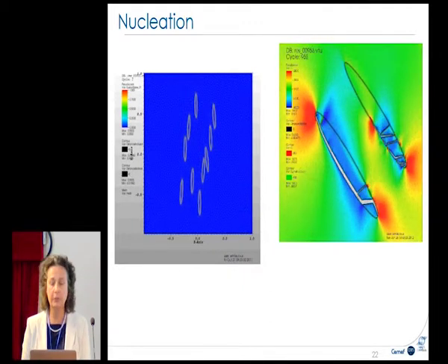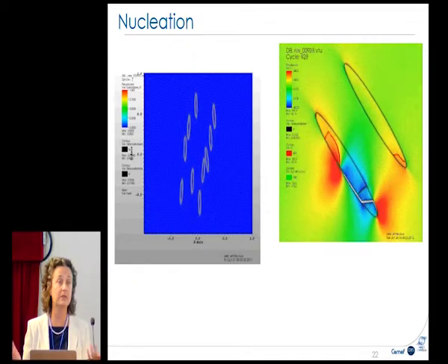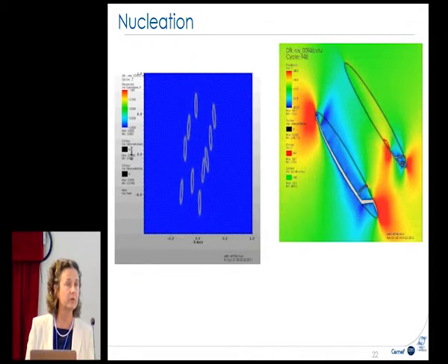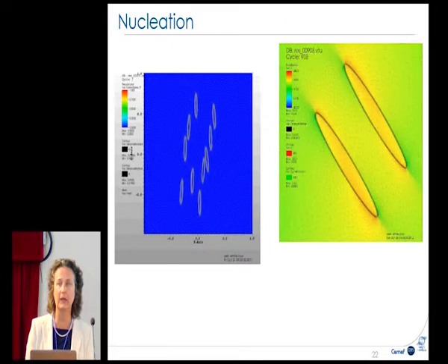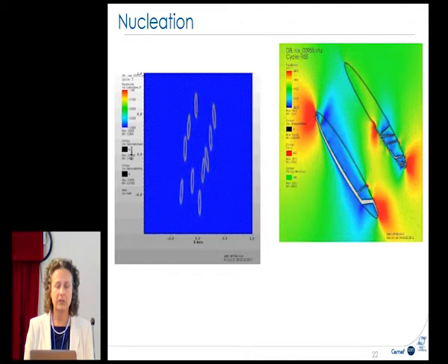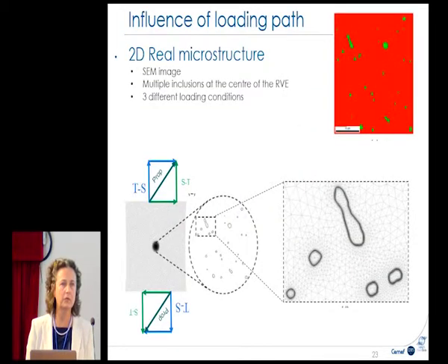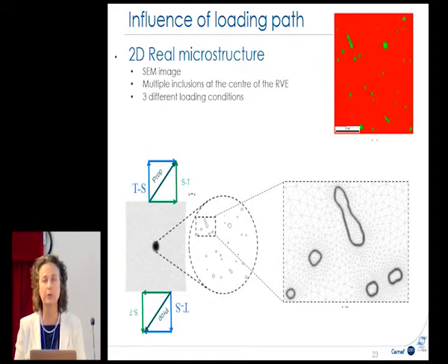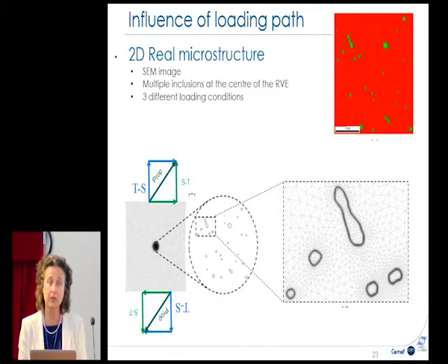For the mechanical properties, each domain has its own properties. For example, the matrix could be elastoplastic, the inclusion could be rigid plastic, incompressible. But for the void, the incompressibility is completely out of scope because we can have 10 times the size for the void, so it's not incompressible. So we have to add another behavior. So perhaps we have 3 behaviors, and we have to mix the properties at the interface here.